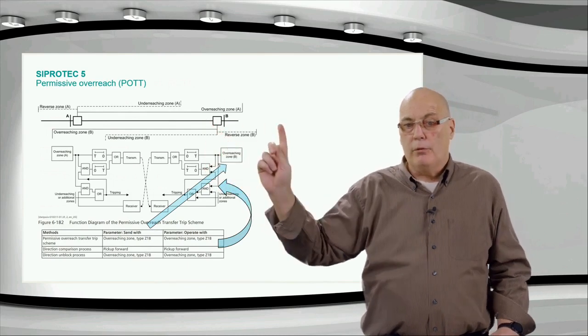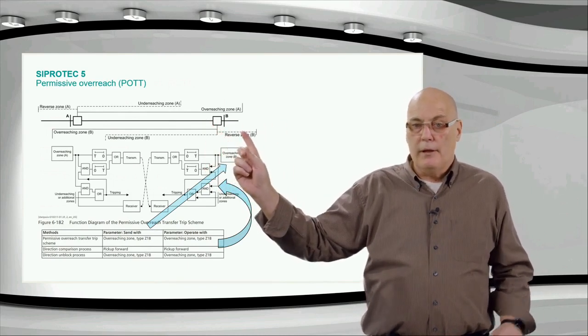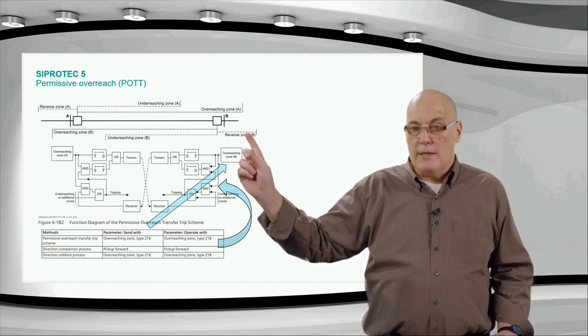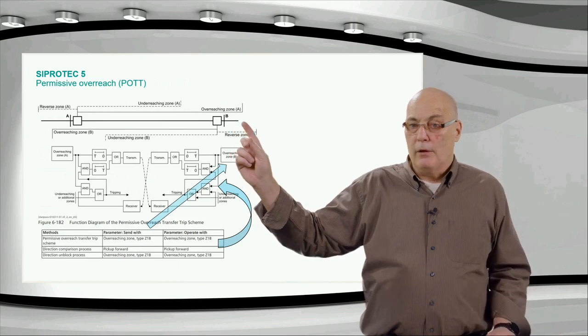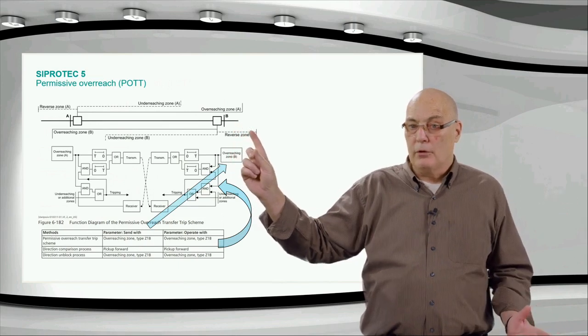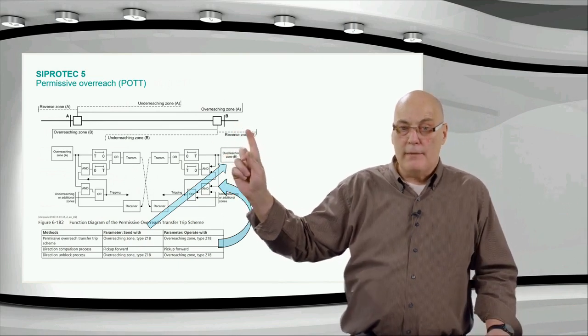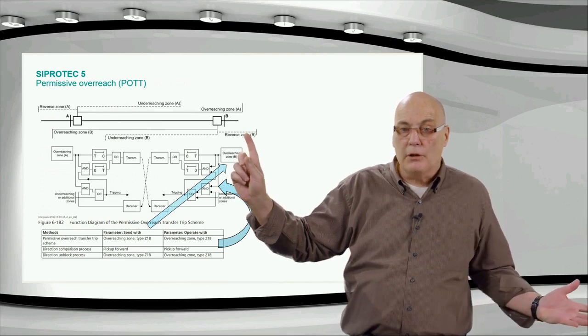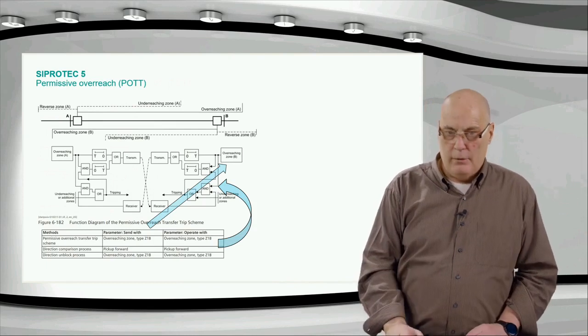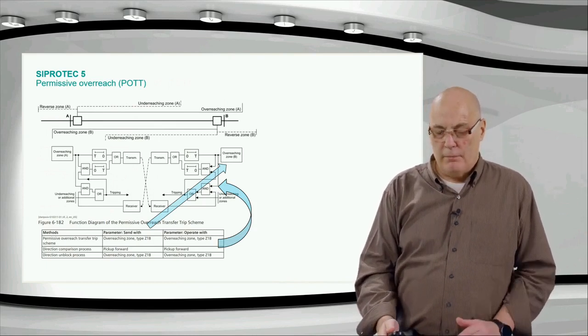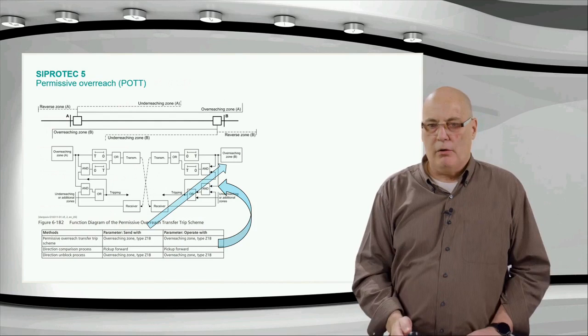If the fault is reverse, over here, the remote side would see it, and zone 1B would send. The local side would not see it in its forward zone, would not trip, okay? But the local side would not send, it's reverse. So only one side sends here, and the receiving side will not see the fault in its zone 1B and no trip. So the system is stable. Also, it's a direction comparison scheme effect, not exactly, but almost.